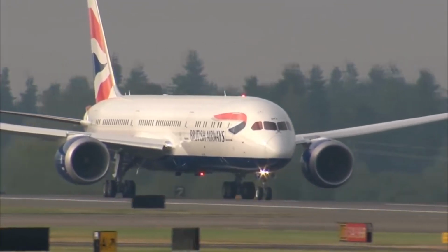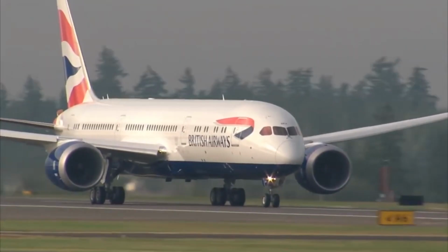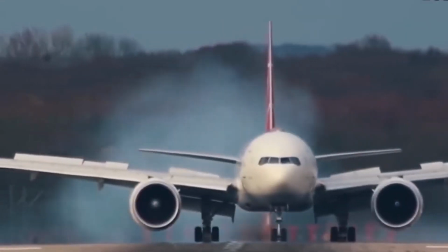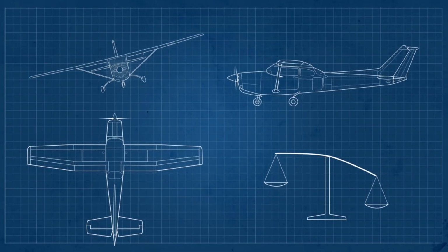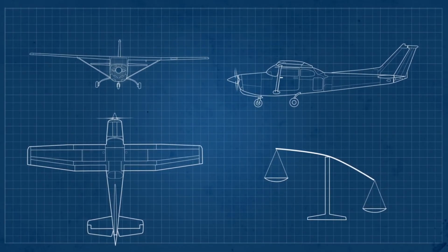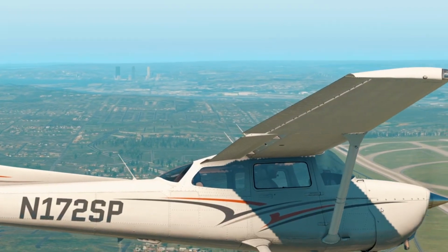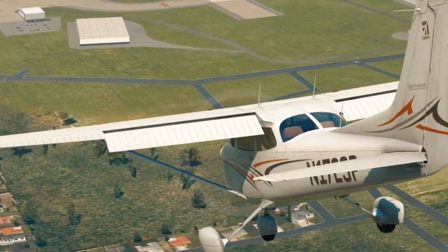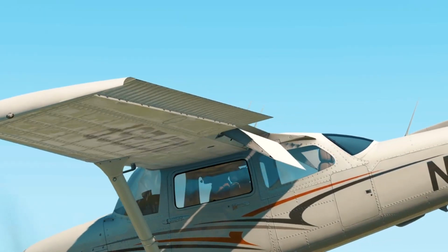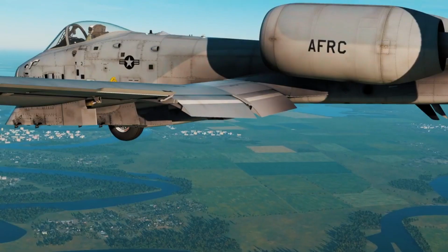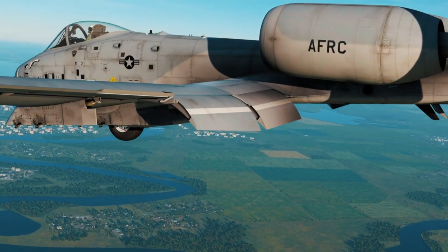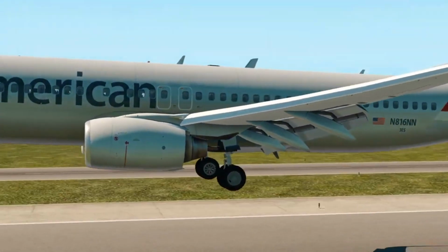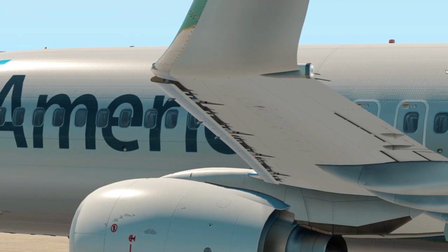Secondary flight controls are intended to improve the aircraft's performance characteristics or relieve excessive control loading. They consist of high-lift devices such as slats, flaps, spoilers, and trim systems. High-lift devices are designed to increase lift during some phases or conditions of flight. The flaps and slats help to slow down the aircraft for landing and help to reduce the ground roll on takeoff. The trim control surfaces reduce the effort the pilot has to apply to fly the aircraft. Spoilers assist the pilot in roll and speed and lift reduction.